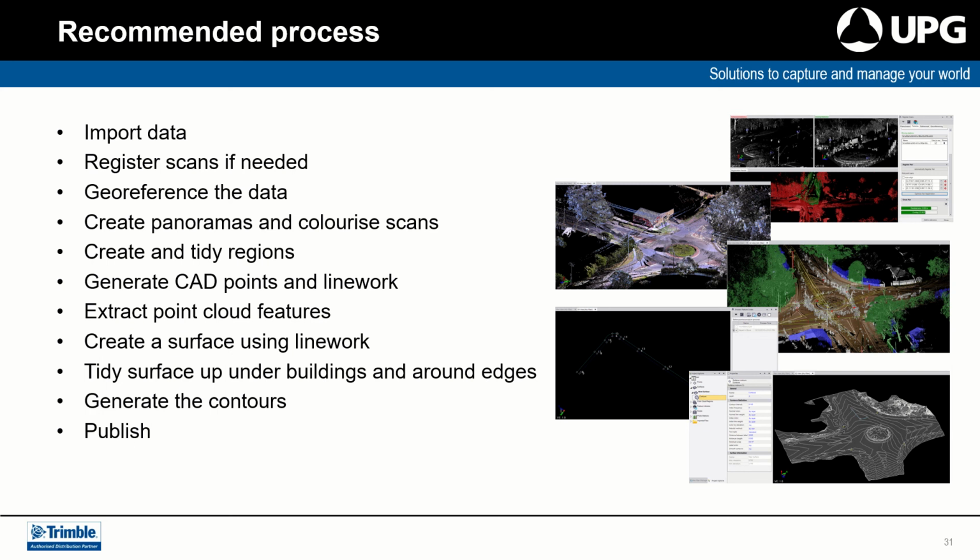So again, don't feel that this is a hard and fast rule for processing the data. It's just a recommended process. Once you've done this step, I would recommend processing the panorama and then colorizing the scans. If it's been colorized on import, I would recommend running this step again. So for the X7 and the TX series instruments where it needs to be done on import, I would run this process where you process the panoramas and then recolorize the scans with those processed panoramas to help add to the quality of those general outputs.